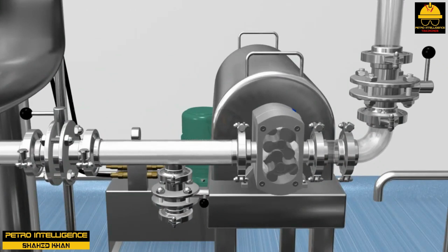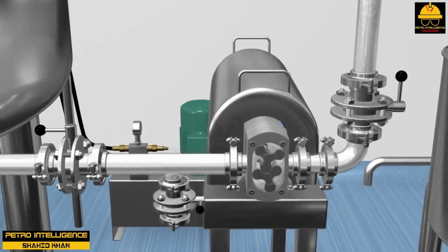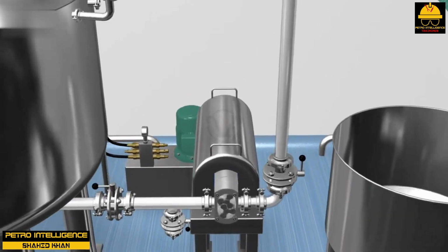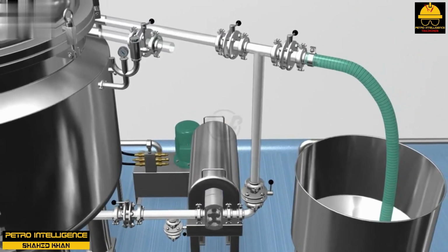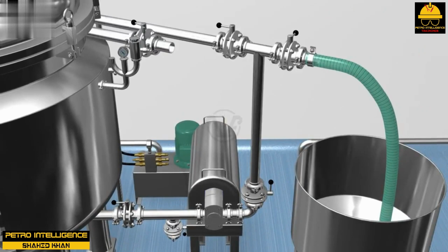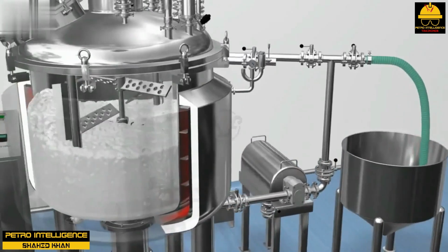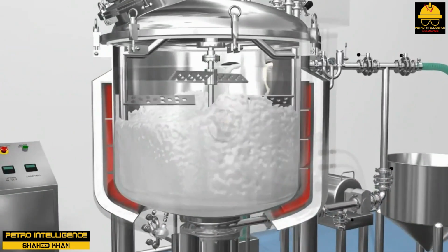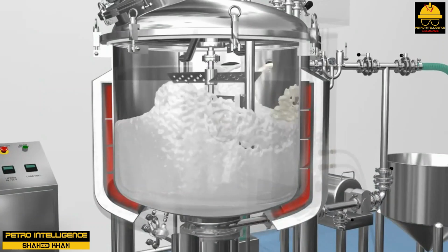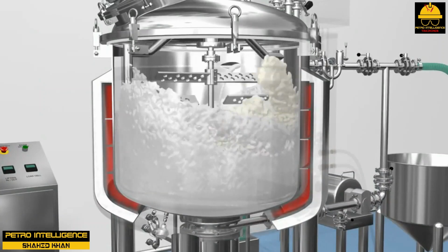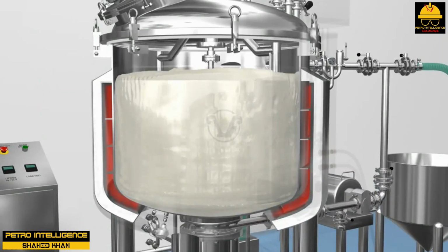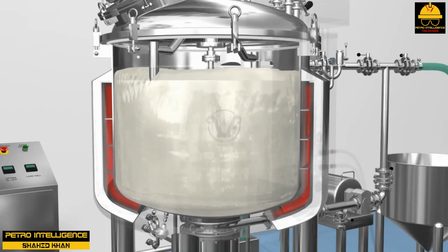Other considerations that must be taken into account are how much agitation is required to produce a uniform reaction mixture, what type of heat transfer equipment will be needed to prevent excessive fouling of the heat transfer surface, the minimum size of reactor that is needed to obtain the necessary reaction time, and whether a catalyst is needed to promote the reaction and how will it be added to prevent a localized reaction.